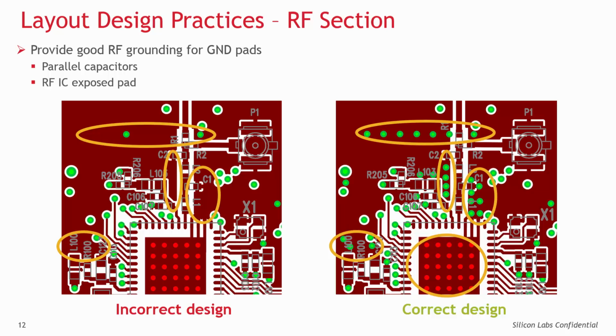In the reference designs, there are 25 vias for the 7x7 mm sized package ICs, each with 10 mil diameter. The paddle ground should also be connected to the top layer GND metal if possible, to further improve RF grounding. This may be accomplished with diagonal trace connections through the corners of the EFR32 IC footprint.